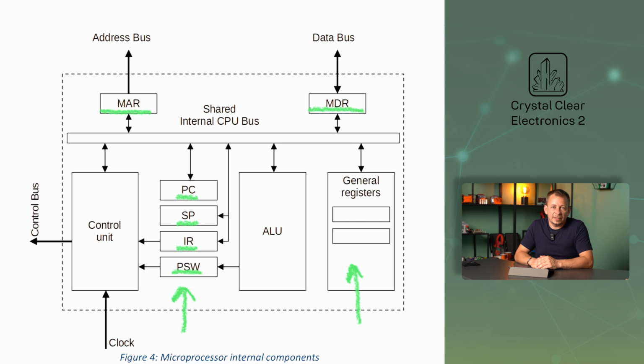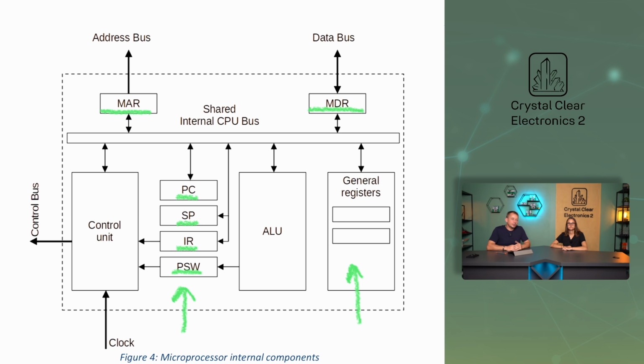In addition to special registers, there are also general-purpose registers. Let's look at an example to understand them. Let's assume that we allocate space somewhere in the memory for 3 variables and give them the following initial values: a equals 0, b equals 3, and c equals 5. At some point during the execution, the microprocessor must perform the following simple addition: c equals a plus b. The general-purpose registers may have different names in different processors, but for now, we'll call them R1, R2, and so on.